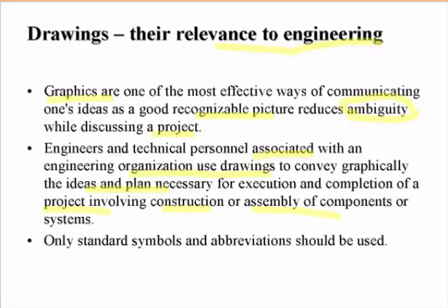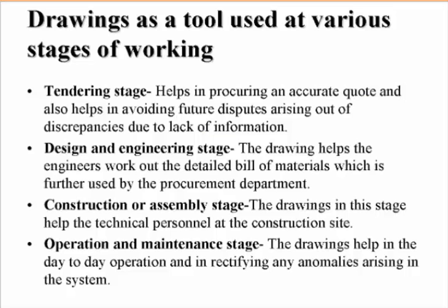of components or systems. Now, only standard symbols and abbreviations should be used. So anyone that picks up your drawing must be able to understand it. Now, drawings are used as a tool at various stages of working. Firstly, the tendering stage. This helps in procuring an accurate quote. Otherwise, the people can't give you an accurate quote. It will also help in avoiding future disputes arising out of discrepancies.